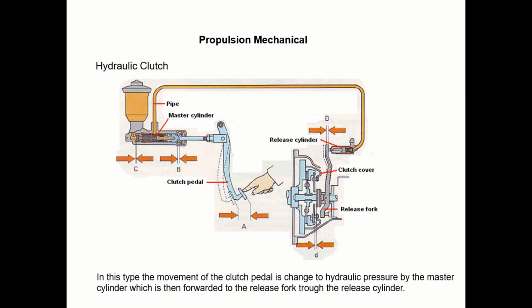The main components of the hydraulic coupling unit are: one, the pump impeller, a pump mechanism that generates hydraulic power to the fluid. Two, the runner turbine, a mechanism for capturing fluid hydraulic power generated by the pump impeller. Three, the stator, a mechanism for regulating the direction of fluid flow so that adverse flow does not occur, but instead a favorable flow so that an increase in moment or torque is obtained.